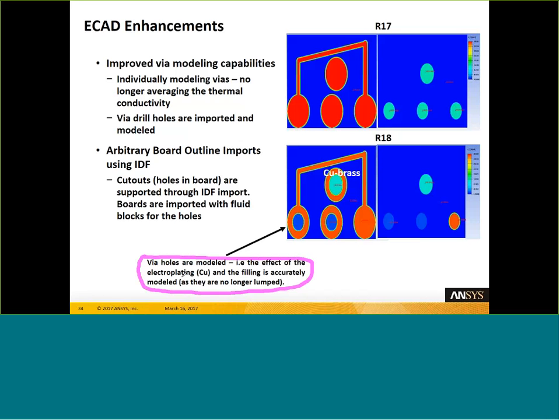Additionally, when you're importing your IDF, you can bring in cutouts or holes in your board, and this is supported now through IDF import. And the boards are imported with fluid blocks for the holes.